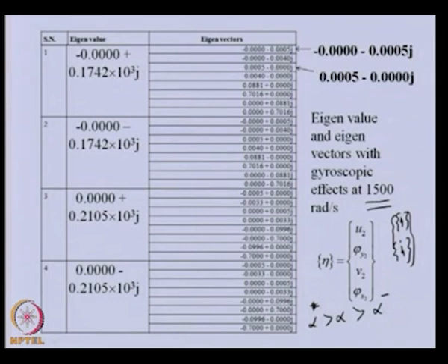But when we consider the damping, especially like fluid film bearing, we will see that both quantities will be complex, and then plotting of the mode shape will be more difficult in that case. Now, we will take up another case in which we will be mounting a flexible rotor on fluid film bearing, and through one example directly we are explaining how the fluid film bearing elemental equation can be clubbed with the finite element equation of the shaft system.